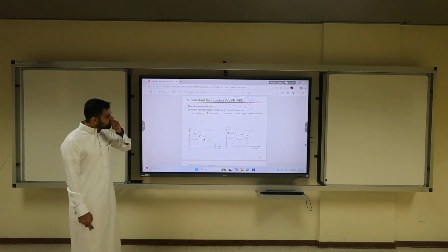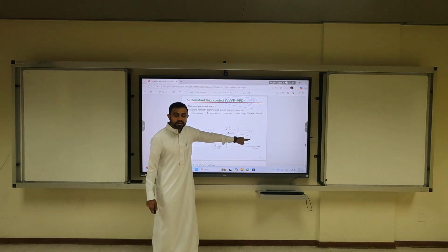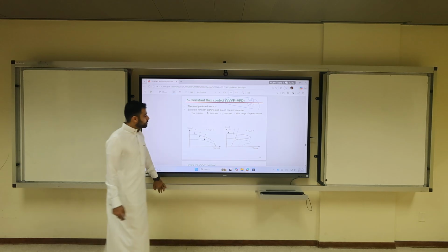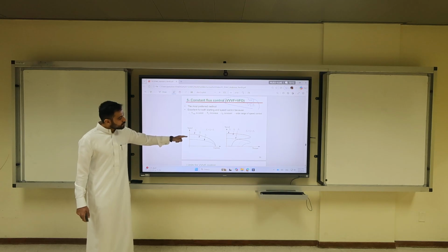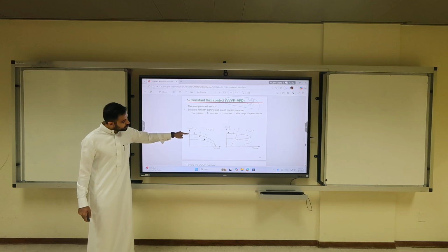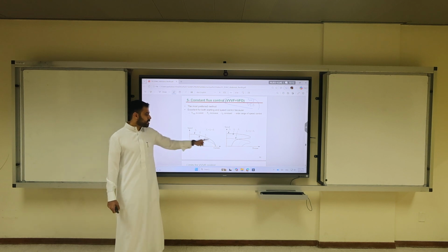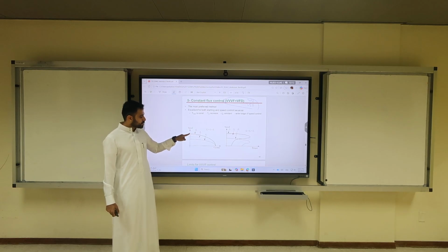And as you can see with V over F, if you look at the torque, it's fixed constant as long as V rated is not achieved. If we achieve V rated, we have to drop because we enter the flux weakening curve. What will happen to the current if we increase the frequency for the same speed? Not constant. So this is speed versus current. For that frequency, for the same speed, you get lower current.